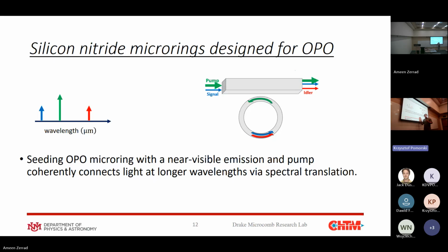This microring resonator is a silicon nitride material. As I told you before, when you have light interacting with a Kerr-type material, such as silicon nitride, you get processes such as four-wave mixing. That's very interesting for us because four-wave mixing is what we propose for parametric oscillation. So what happens is that the pump light and signal travel through this ring, interact with the Kerr-type material, and that results in the generation of signal and idler sidebands, which get outcoupled by the same waveguide.